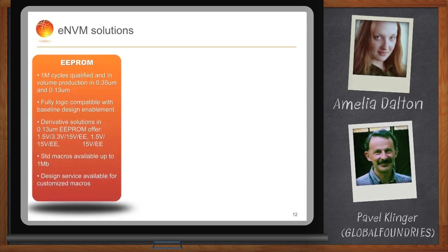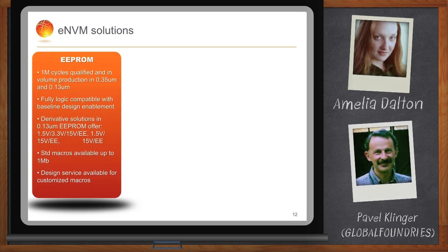One is the E2PROM devices. Those devices are targeting applications that need an extremely high number of program erase cycles, or something that the engineering community calls endurance, and extremely low power consumption. We do have such devices offered at 0.35 and 0.13 micron technology nodes.